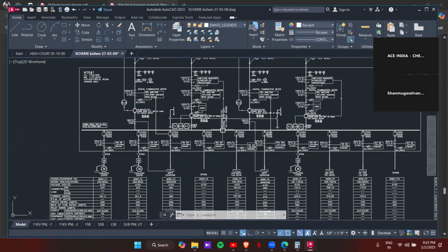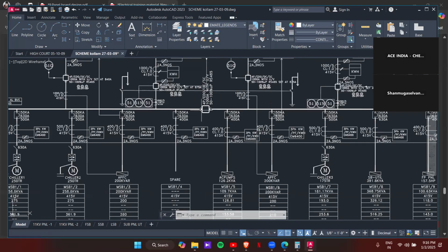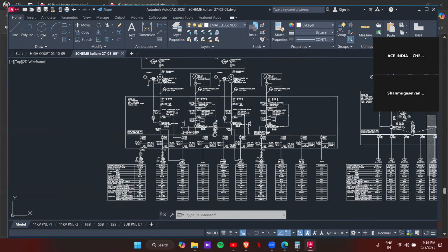Okay, in case you require it, or again it's not necessary, but in some cases this is the load manager system. That's why we have an ACB in between. If there is no ACB, we will have a single system. In order to isolate the bus bar, we are using an ACB here. So that transformer 1 and DG1 will be covering this part, and transformer 2 and DG2 will be covering the right hand side. That's it.